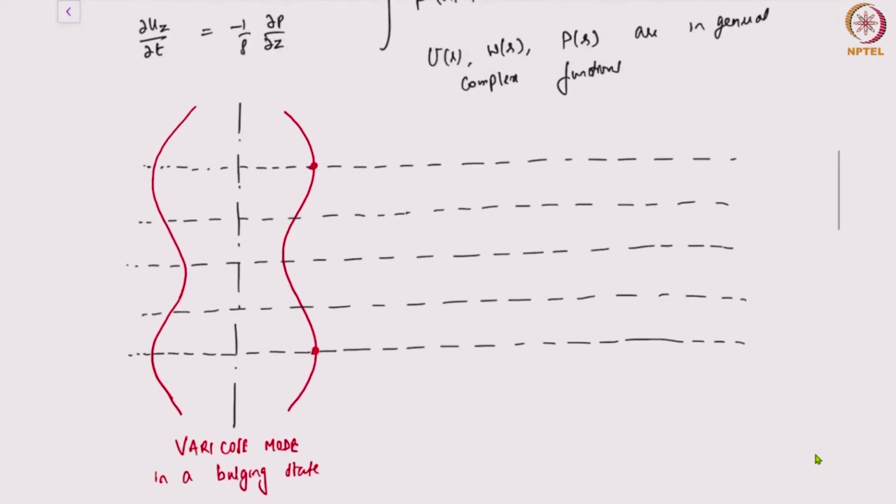Meaning it is at that stage where the crests are becoming bigger and the troughs are becoming narrower, right? If in such a situation, what you would expect is that you can actually only bulge out if fluid were to travel from the troughs into the crests.